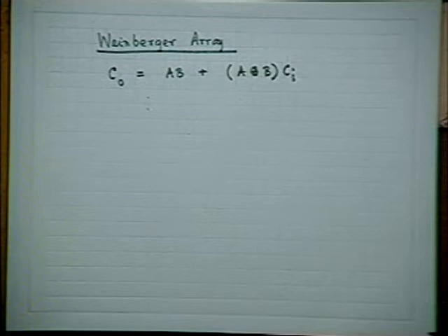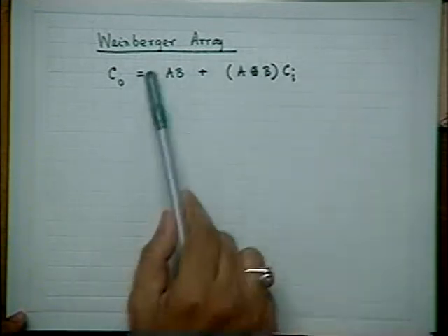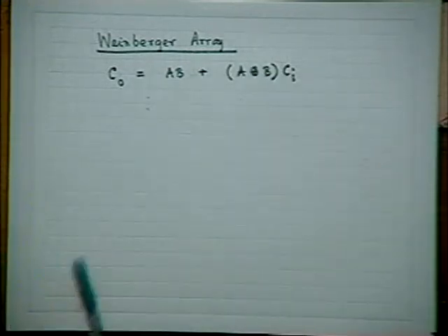So here you could really write it down in the form of sum of products, minimize and do the PLA. This is one approach, whatever already discussed. But in certain cases, this is not convenient, particularly from minimization point of view.